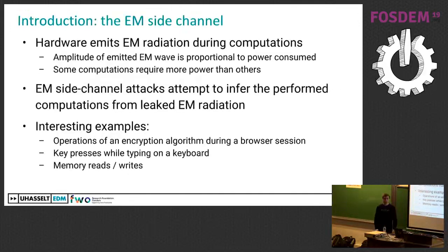Now, for those of you who don't know what side channels are all about: when your hardware is performing computations, obviously there is some current going through a conductor, which will in turn emit an electromagnetic wave. This is just the way that physics works. And the amplitude of this emitted electromagnetic wave turns out to be proportional to the power that is being consumed. Obviously some computations require more power than others. If you're mining Bitcoins, then your computer will probably be consuming a lot more power than when it's just idling.